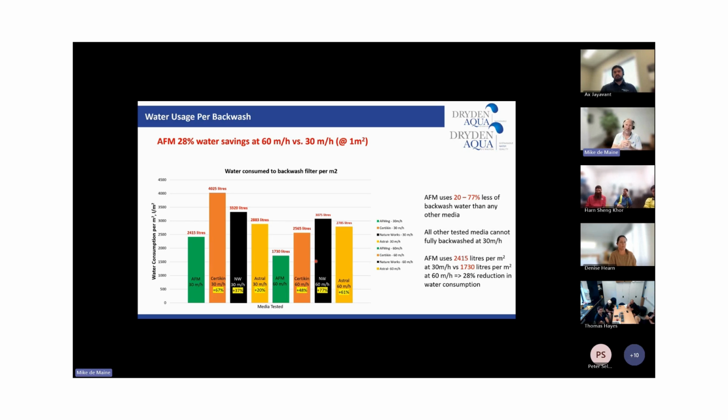Whereas all the other medias use a hard crushing technique. If you hold their media in your hand, you'll see a lot of sharp shards and flat pieces of glass. You can imagine when those go into backwash mode, those flat pieces and sharp shards just stand upright in the water column and end up dropping down in your filter bed. Over time, that creates an increase in filtration pressure, because those flat pieces and sharp shards end up at the bottom of your filter, blocking it up. So not only is the dirt not being released, but the glass itself is also creating problems for you.